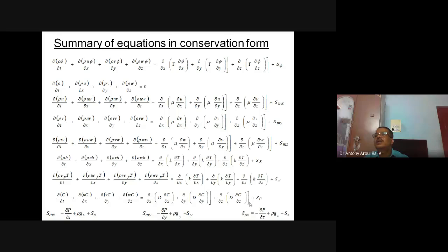So those types of things you cannot use in CFD. In CFD, since the number of equations handled per node is very much higher, it is better to go for iterative methods only. Then only you can solve the problem of memory. Otherwise, it is going to be trouble. If you use direct methods for CFD, definitely it is going to be trouble.